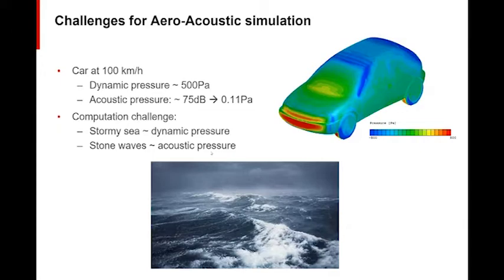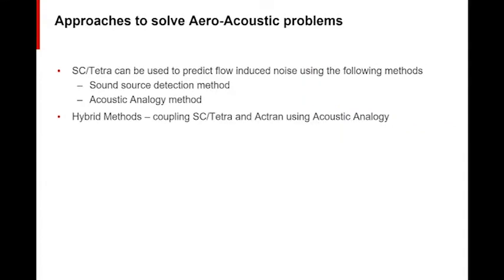The sound source detection method is just like a post-processing of the CFD results. The advantage of this method is that it can use the steady-state results to estimate the noise sources. And we have three methods